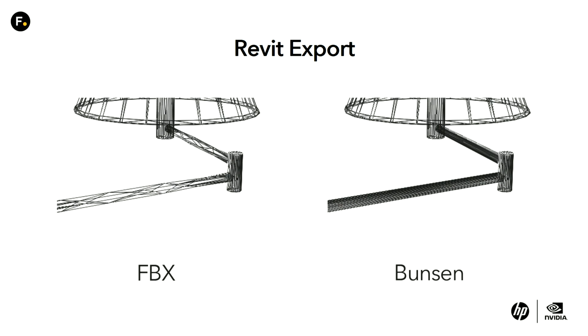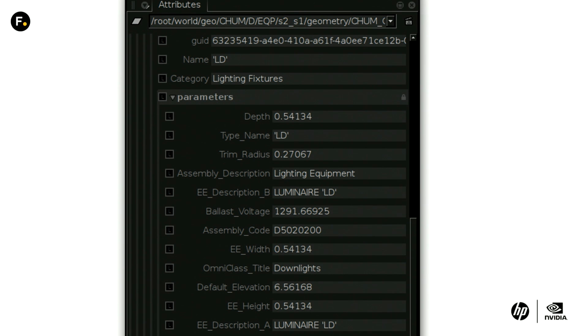Some of you may have seen this before. We found if you took the native FBX Revit export, you quite often get these little crushed polygons with cylinders and things that need a lot of manual cleanup. We were able, with a bit of work, to get something with better consistency out the gate without increasing the weight of the models too much. So hopefully that removes some of the cleanup that you have to do manually later. But the second reason is to make sure we preserve all of the metadata and other properties and annotations that you have attached to these items.